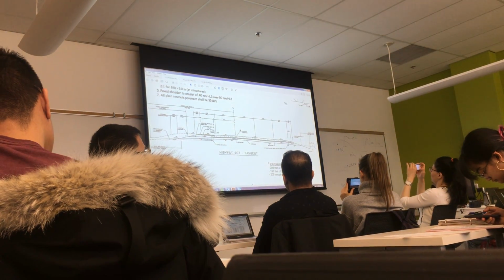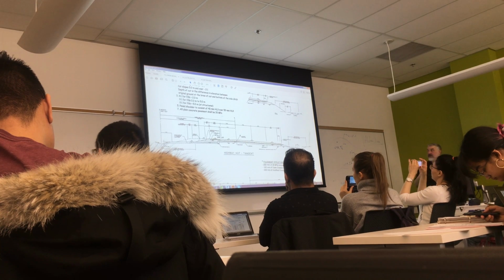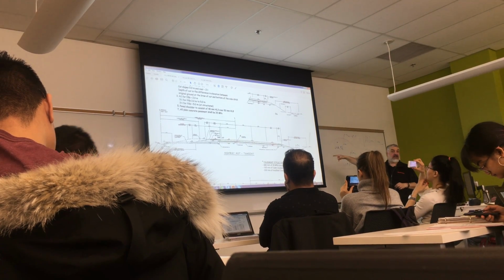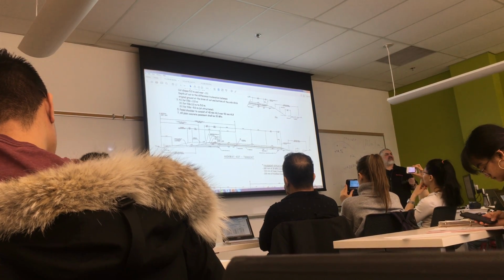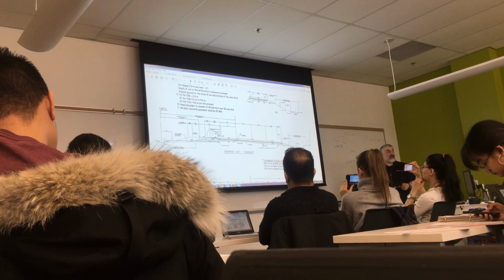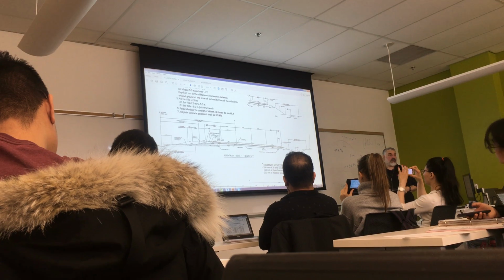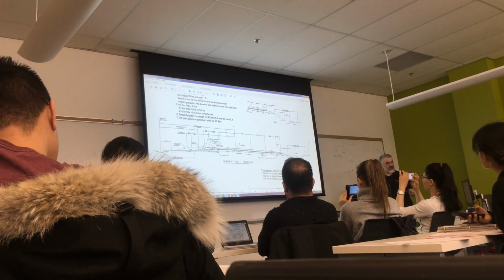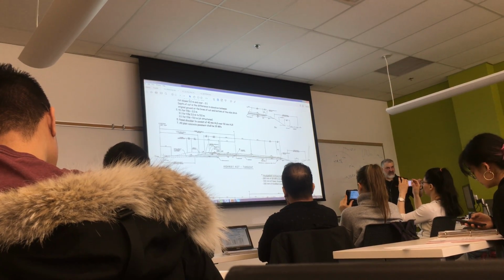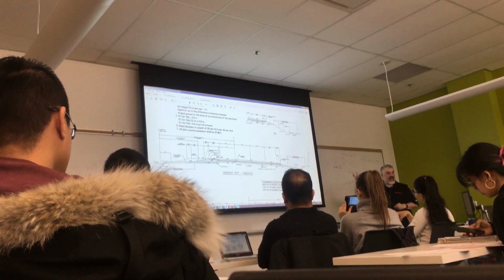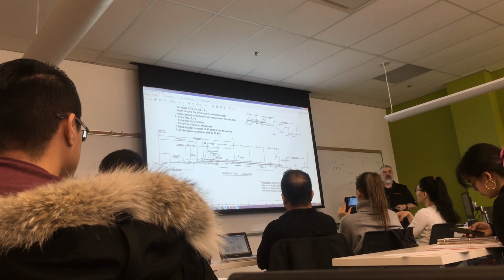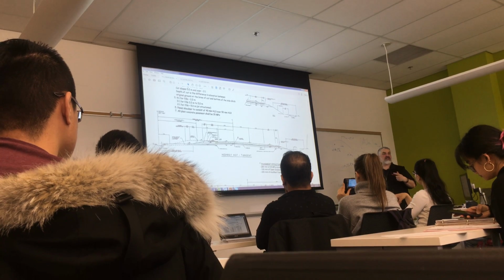All the numbers that were used to draw the cross section are annotated on the drawing. Think of it this way: if you needed that information to draw it, then the contractor needs the same information to build it. So it must be on the drawing, because you're not supposed to scale drawings, remember? The picture is there for reference. It's the data, the numbers, the text that's important. So if you use a number, make sure that's annotated on the drawing.